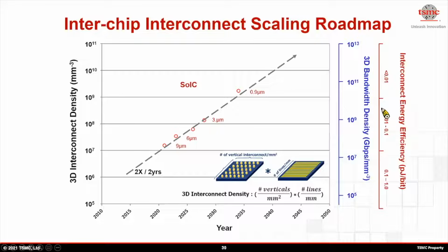And the second reason was that our process is fairly scalable. We have shown the feasibility of sub-micron pitch bonding. So the schedule for the first few SoIC nodes may be squeezed a bit.